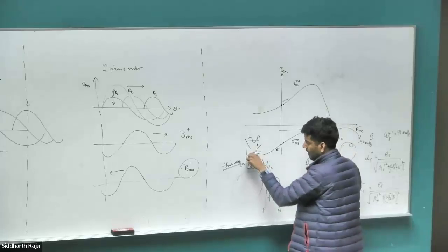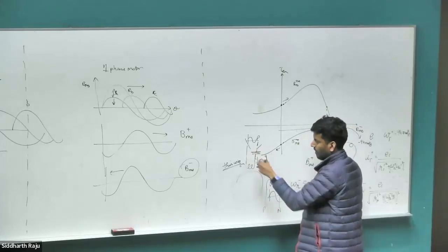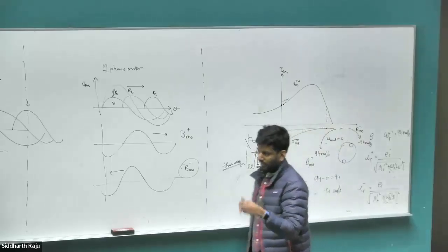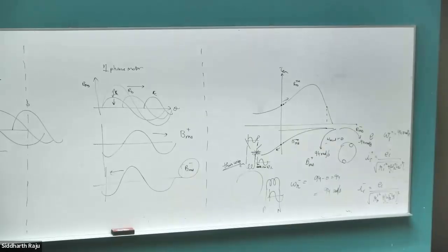But the way to fix that, typically, is that if your fan is not rotating, this capacitor would have blown out. So all you have to do is replace the capacitor and the fan would work absolutely fine. Alright. With that, we are done.